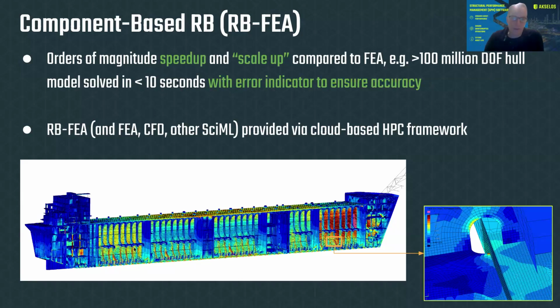At Akselos, we provide this RBFEA framework via a cloud-based high-performance computing framework that includes the training functionality. So you can run this training framework I talked about earlier, where you do the sampling of parameters and so on, create the basis for each component, and create all the interfaces between components, and that all runs on the cloud. The nice thing about that is each component is trained independently, so it's highly parallelizable on the cloud. You can have hundreds or thousands of cores running, training the model, and when you run the solve, it's also leveraging parallelism on the cloud. But of course, the speed up we're bringing is not at all based on parallelizing the compute.